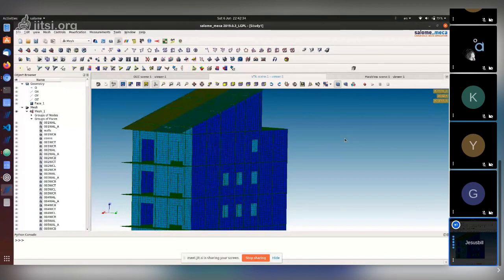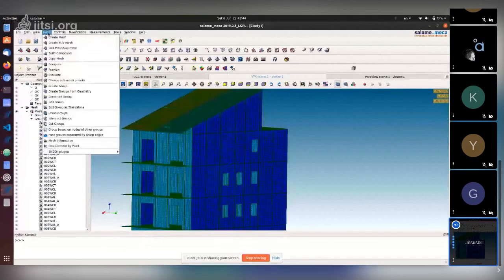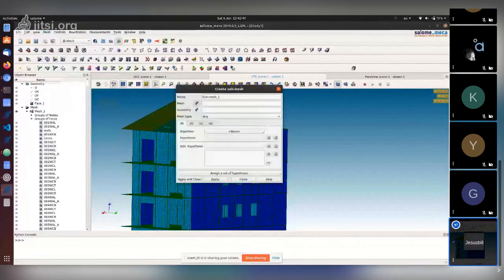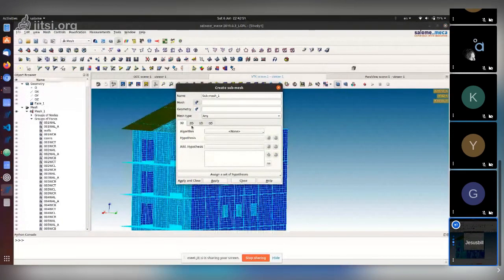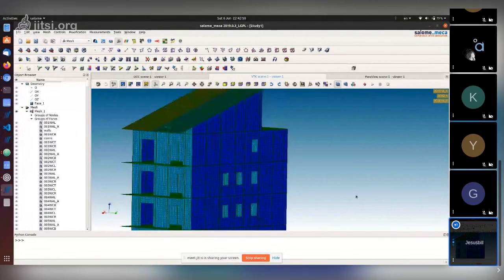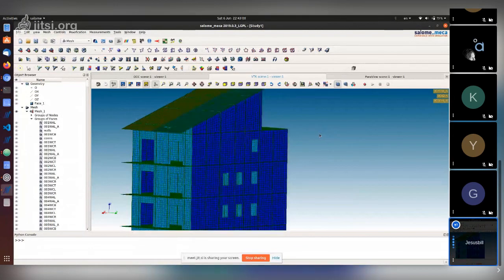I prefer to have a good procedure so that I do the mesh and that's it. You can have sub-meshes. You can select some geometries and tell it how you want them meshed. So in the end, you have a lot of flexibility to select groups that you want with a certain type of mesh. And then it also depends on how you set up your geometry.